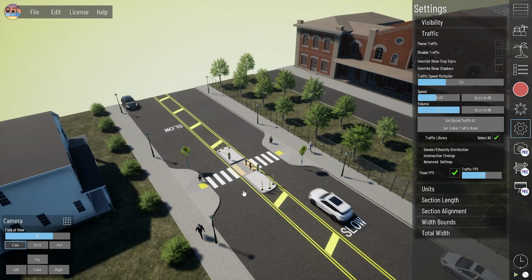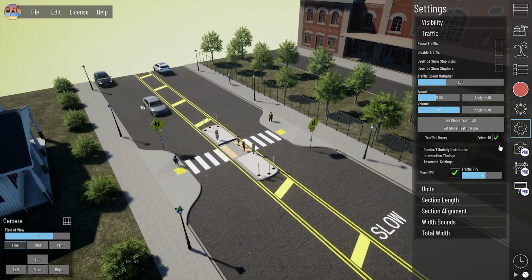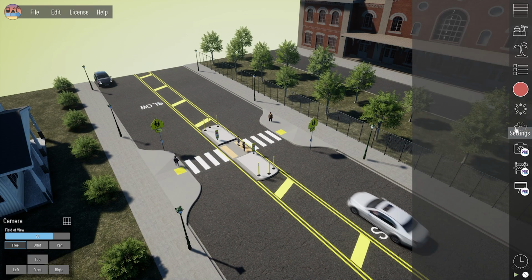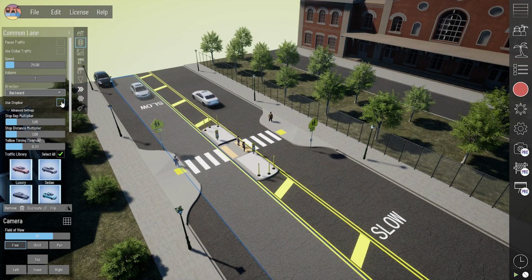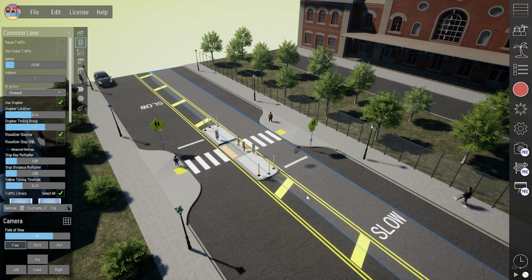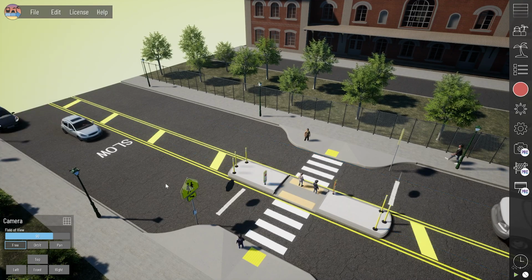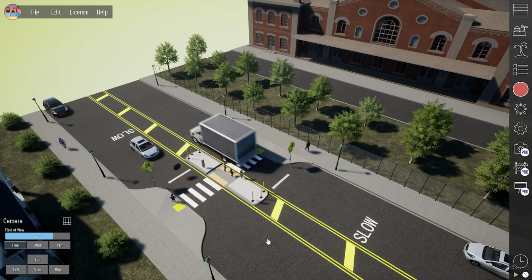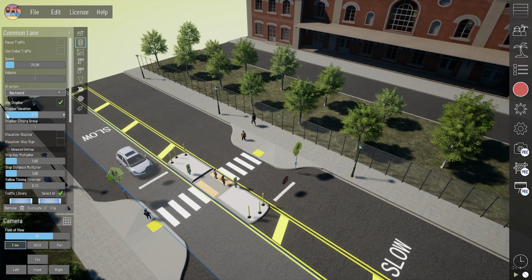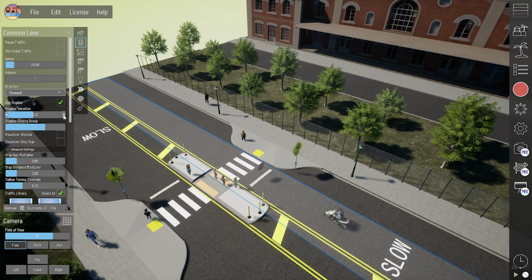Here I've got a project with a mid-block crosswalk and some bump outs and a pedestrian refuge island. Here could be a good case to show stopping traffic. So first I will toggle on my overrides so I can see when I place those. And let's add a stop bar to this lane and this lane as well. And you'll see I've got some stop bars. I can turn the visualizer off here since I've got my global setting on. And I'm going to make a couple of tweaks to my stop bars so these stop a little bit closer to that crosswalk. There we go.